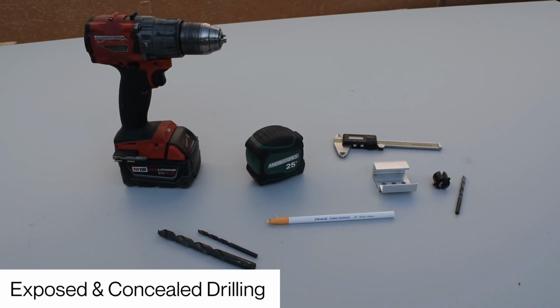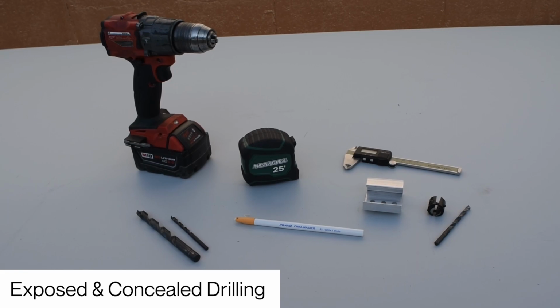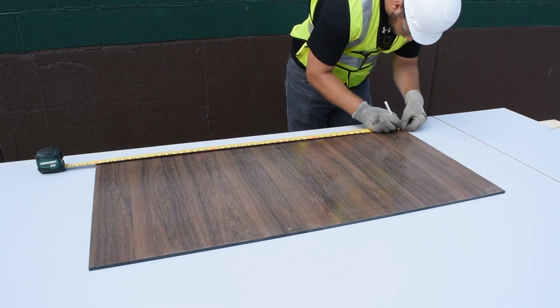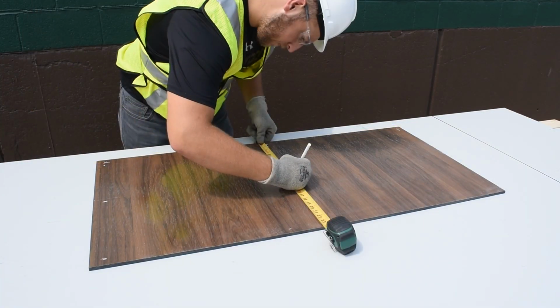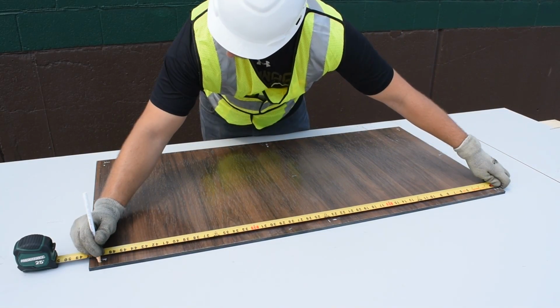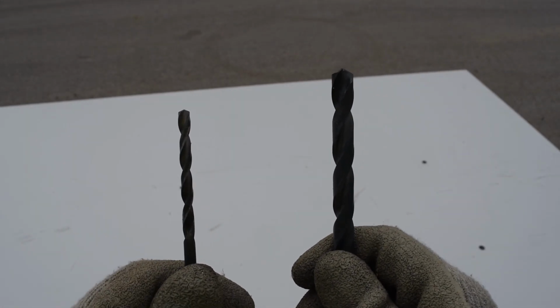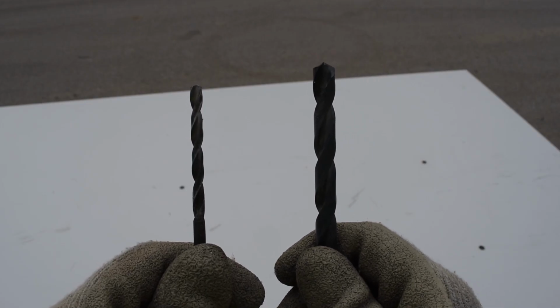The next process that we will be covering is the exposed fastener system drilling and the concealed fastener system drilling. For the exposed fastening system, always review the installation guide for fixed point and floating hole sizes and locations. Measure out your drill locations on the face of the panel. There are 2 different hole sizes. The smaller bit is used for the fixed point and the larger bit for the floating holes.